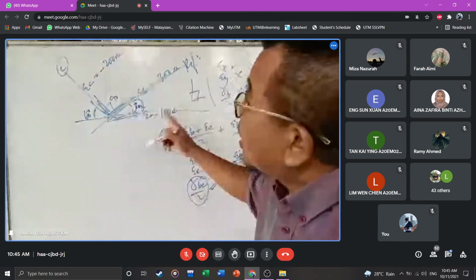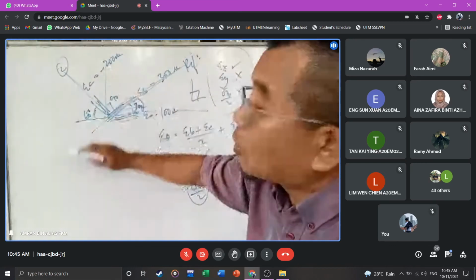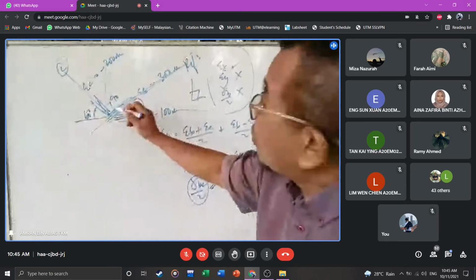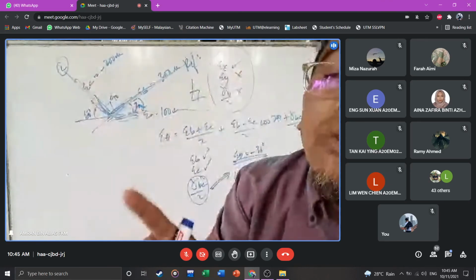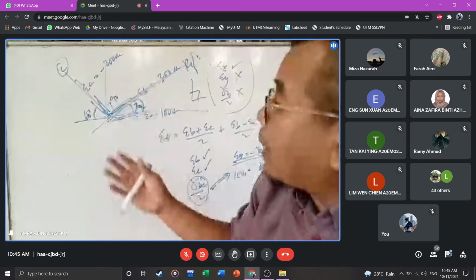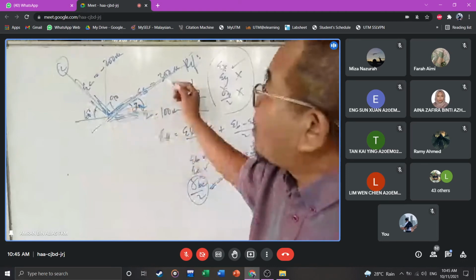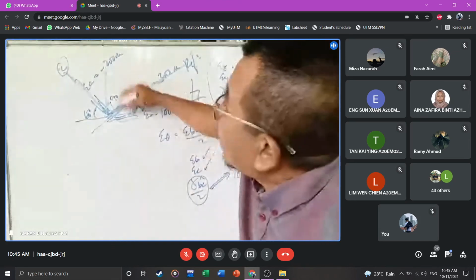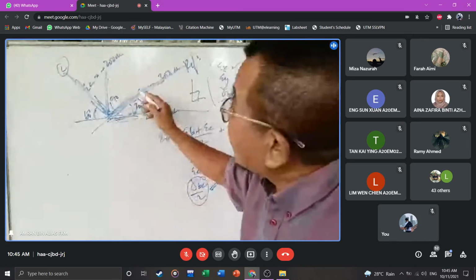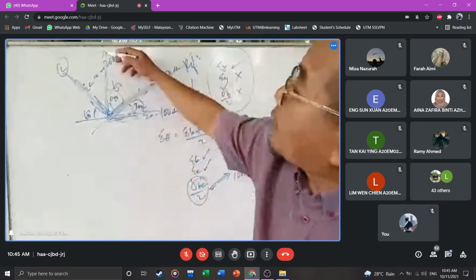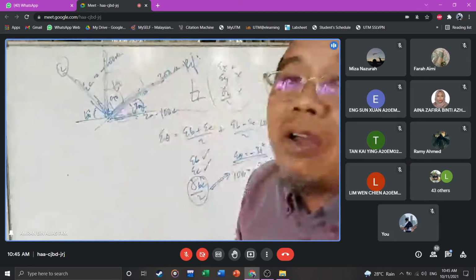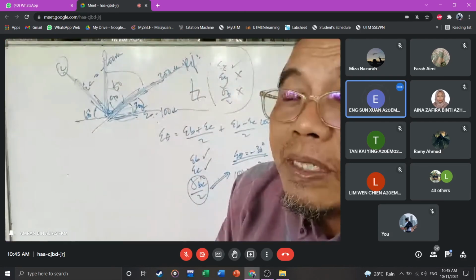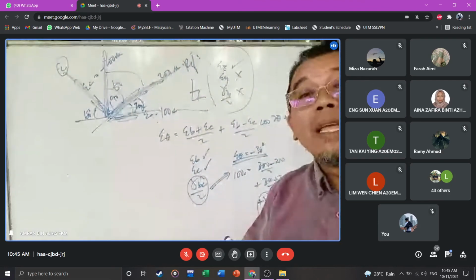If you use XY, in this case, you know only X. I don't know EY, I don't know gamma xy. You have to solve two equations there. Here, you use B and C, you use one equation only to solve gamma. And then you can find back. When you rotate back, when you know gamma BC, you can plot Mohr circle, you can use the equation, you can find EY, right? Yes. From that axis to that is 60 degrees, you can find that. Are you with me, guys? Yes. So that's our topic for today.